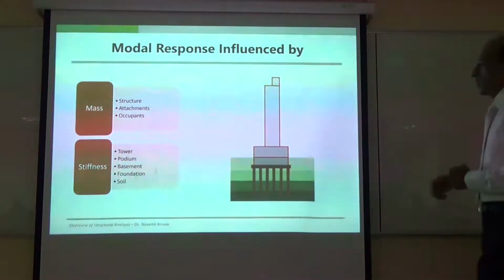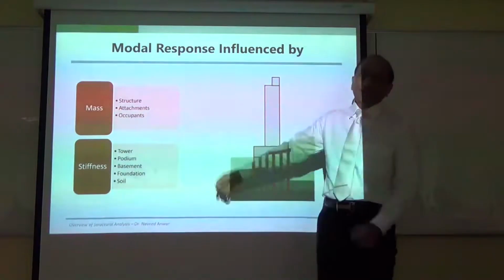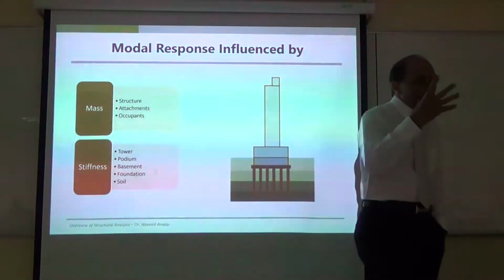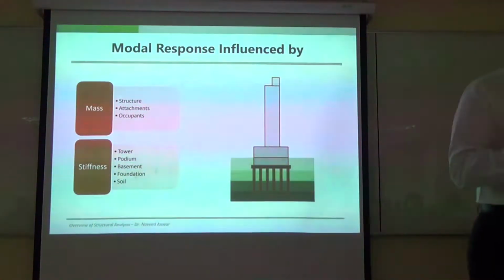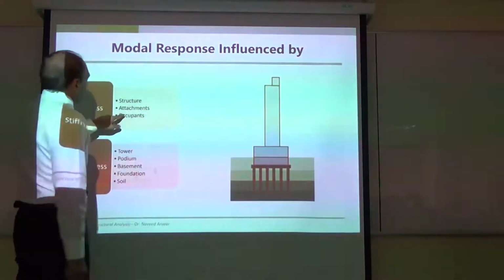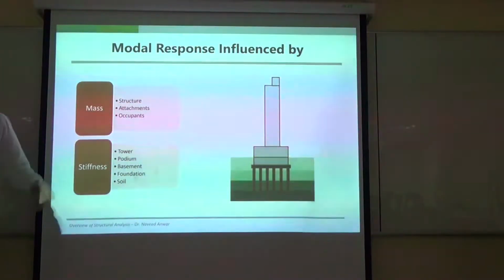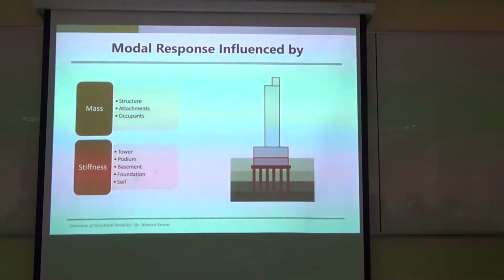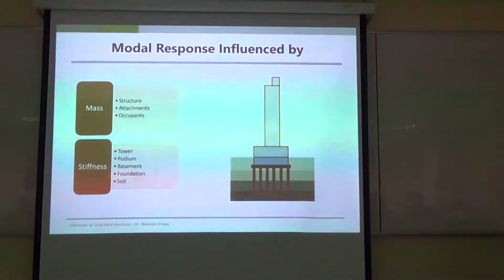Modal response of a structure is influenced by many things. Basically 2: mass and stiffness. Mass is influenced by structure, attachments, and occupants. So if the structure is empty, mass will be different. If it is full of people, like today, mass will be different. When it is full of water, mass will be different. If something is stored here, mass will be different.